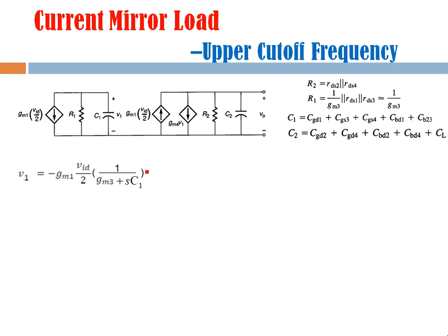So V1 we know, and this V1 will be used to find the net current on this side. And the current here, I0, is a combination of these two current sources. So this part gives current in this branch, and this component gives current in this branch. For this current we have to use the value of V1, and V1 will come from here.